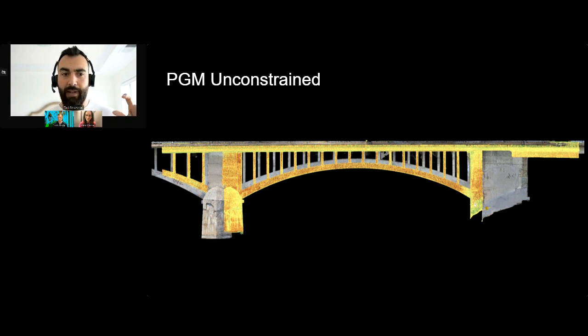So when I bring in the laser scan, you can see the laser scan is the yellow points and the photogrammetry points together. Again, photogrammetry completely unconstrained. That scale error is still there, right? So again, not shocking. We know that photogrammetry has a hard time with scale. I didn't use scale constraints at all here. So we're looking at a direct output from both.